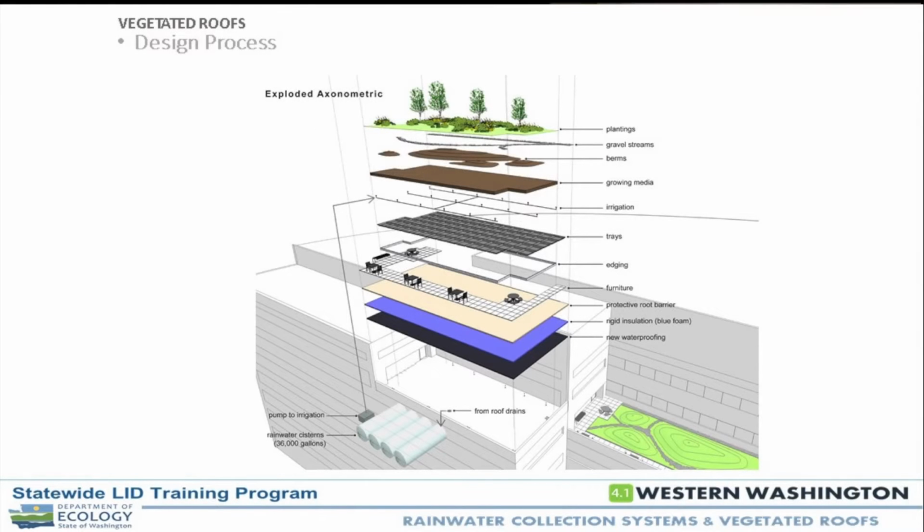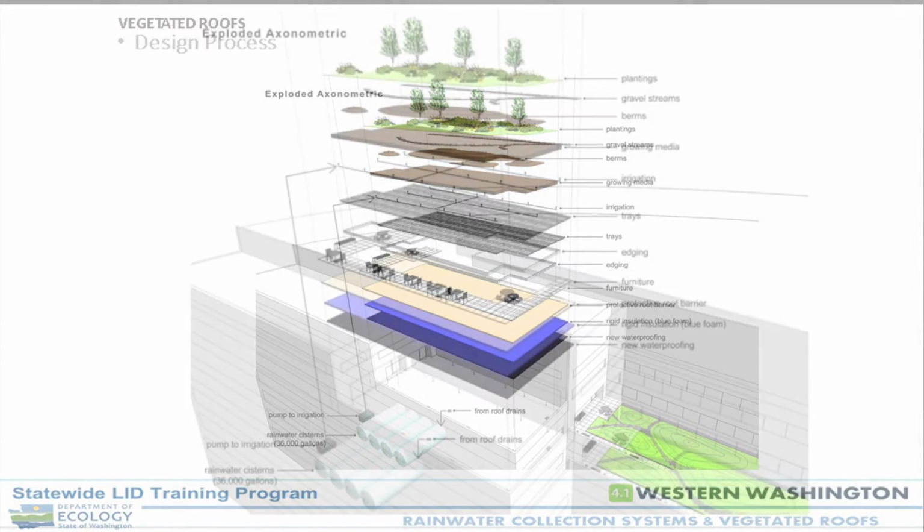This is my one project where I've actually used trays, and we were required by the owner to use them because it was part of a GSA contract. There's certain conditions where you might use trays, if you had a lot of rooftop complexity and wanted to have this sort of modular system. This is a bunch of plastic, and soil is going to be contained within the edging anyway, so breaking it up into all these little units and incorporating a bunch of plastic into a project doesn't really make a lot of sense in that way.